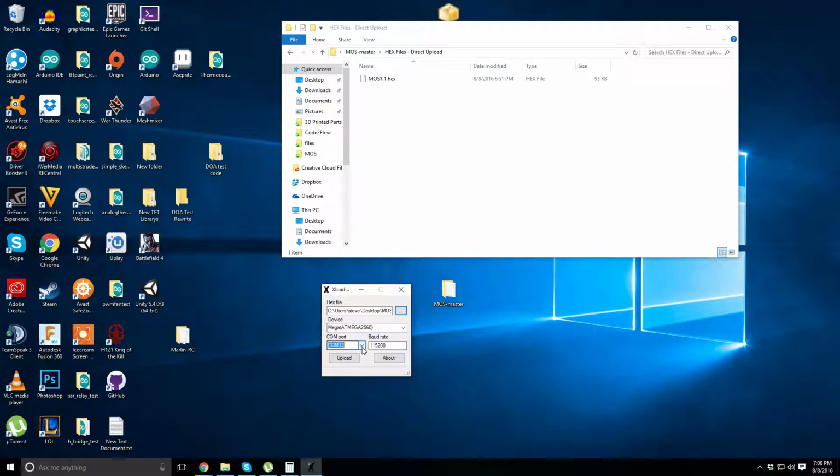After that, you're going to go to COM port, and it will say your COM right here. You should only have one, and mine's COM 14. The last one I uploaded was COM 13. So just hit COM 14. Now you're ready to go. And then all you do is hit upload.